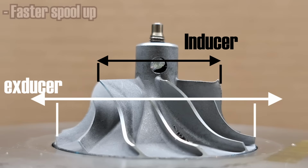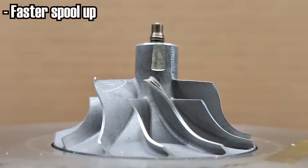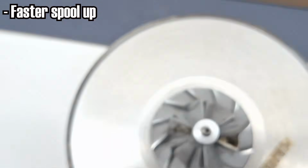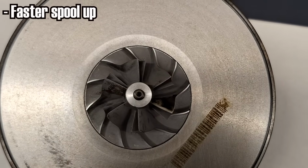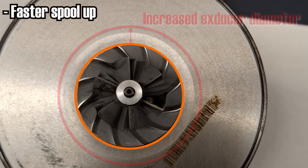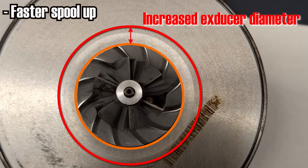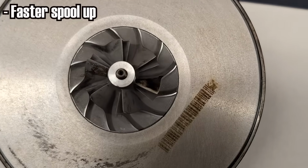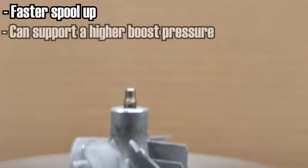Increasing the size of the exducer while keeping inducer size the same has the opposite effect. It makes the turbo spool up faster or reduces the boost threshold because it increases the gas speed. This happens because air is being spit out radially. So a greater exducer diameter means that we have a larger wheel edge speed for the same shaft speed. Because with a larger diameter, the outer edge must cover a greater distance within the same time, leading to increased velocity. This increased wheel edge velocity means that the gases exit at much higher speeds, which means that the turbo builds boost faster. Another benefit of an increased exducer is the ability to support a higher boost pressure.